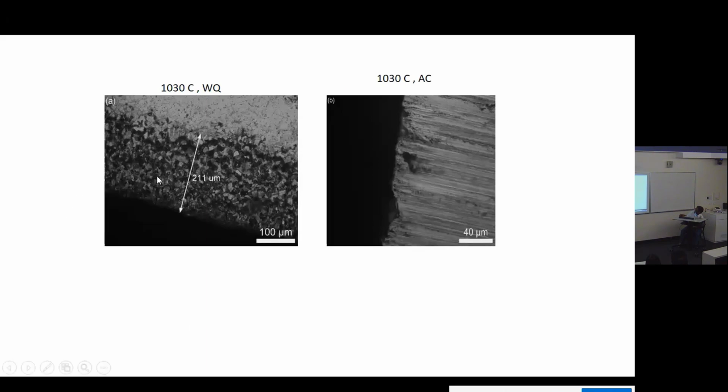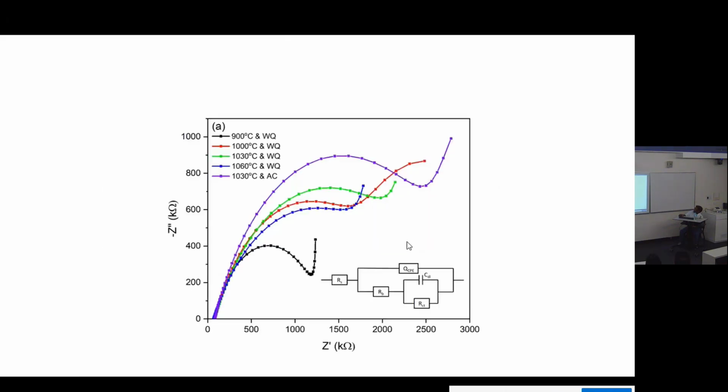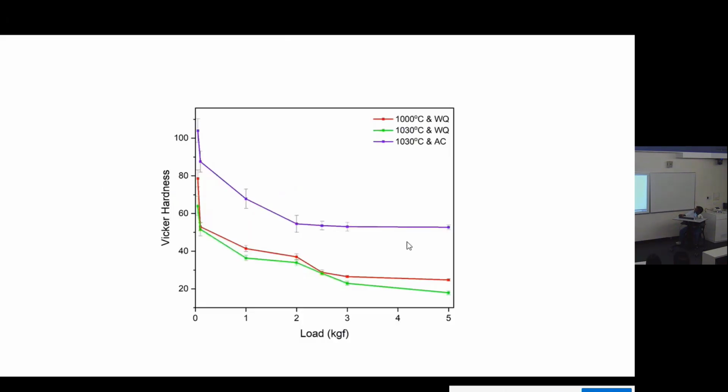And then when it was water quenched, we also think that it produced a large amount of porosity. I think the dissociation of hydrogen and oxygen, we believe that hydrogen produced a huge amount of porosity on the surface. Whereas the air-cooled one had enough time for the air to diffuse out of the surface of the metal, and it was mainly all right, I think.